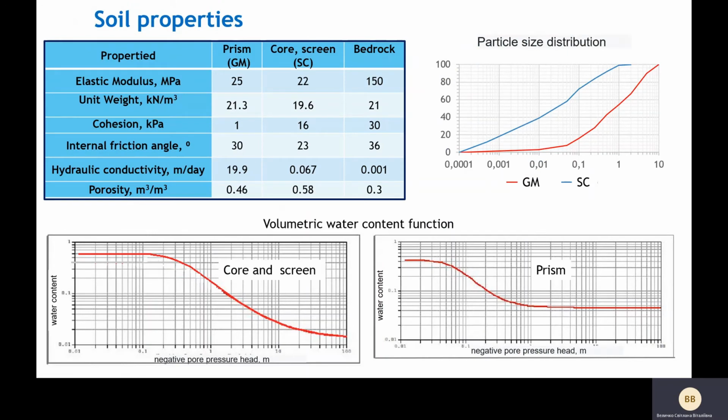The mechanical properties of the soil for the Mohr-Coulomb model were obtained as a result of field review and laboratory processing. The volumetric water content function, hydraulic conductivity function, and residual water content were taken from literature sources using the particle size distribution of the soil. The foundation was assumed fully saturated.